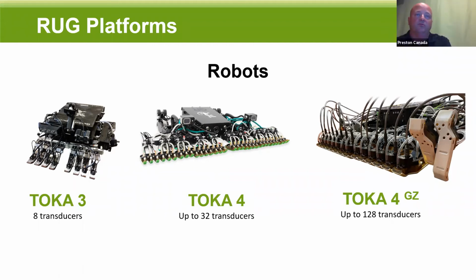So flaking paint would be an issue because ultrasonics could not get a good signal through the flaking paint. If you have well-bonded coatings that are reasonably of thickness, so when I say that, 50, 60 mils of coating thickness, we can scan through. But the surface does need to be fairly clean.